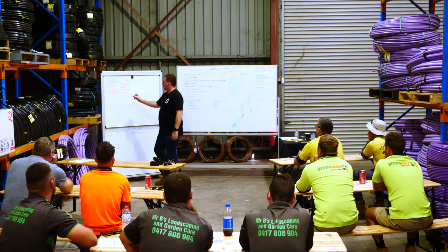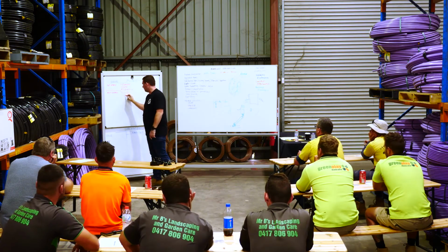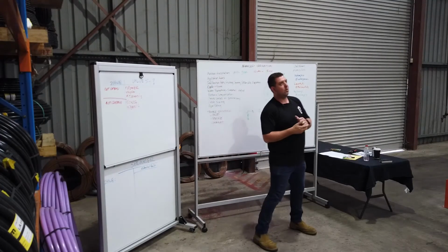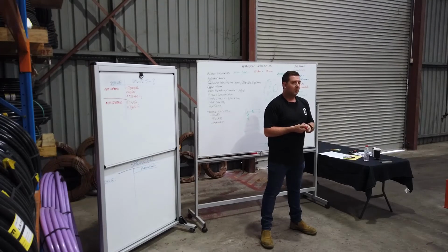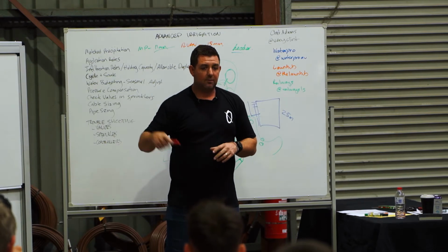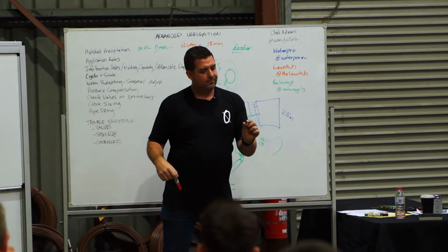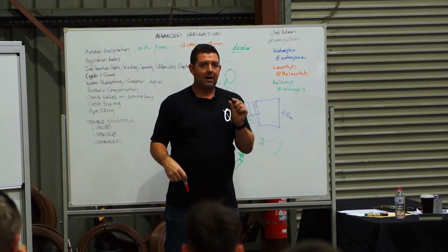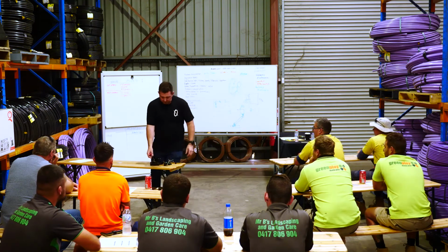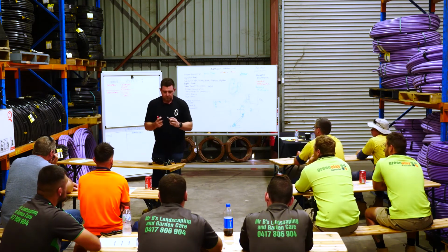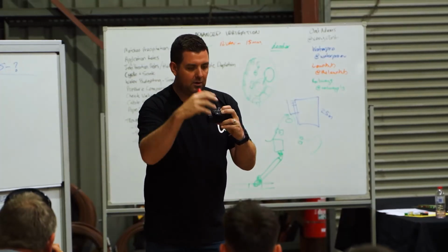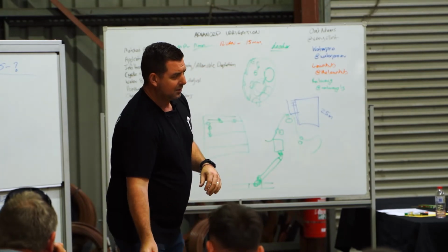Now, debris, as you said, is probably, aside from damage, the most common. The amount of times I've found, it's usually the last valve on the manifold, like a 7 mil white aggregate stone somehow is in the last valve, and it sits under the diaphragm because it comes in on top of the diaphragm, I think, actually. And the way these diaphragms push up and down to open and close, the rock won't let it stop, won't let it close.